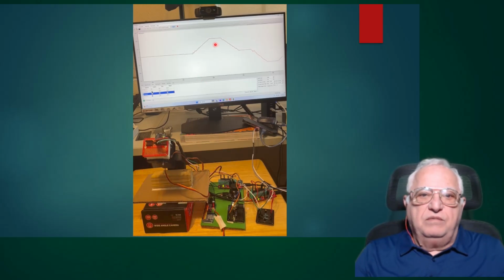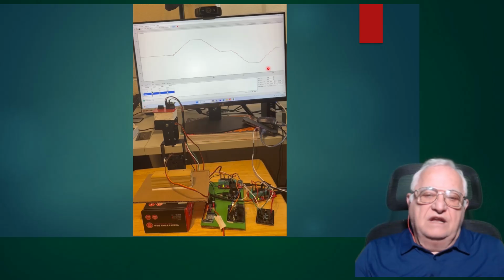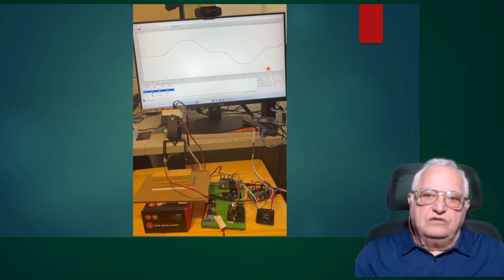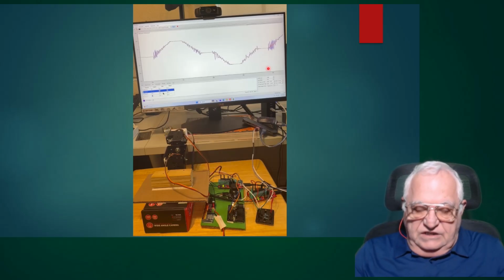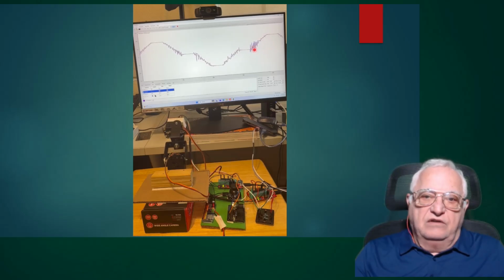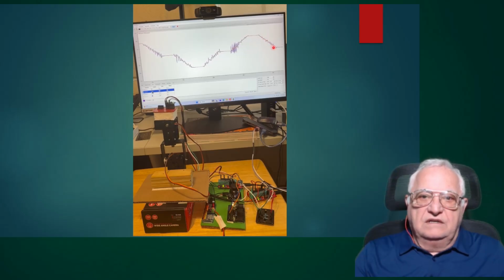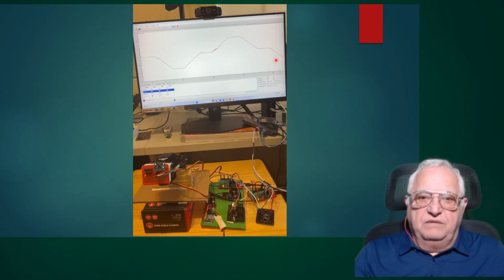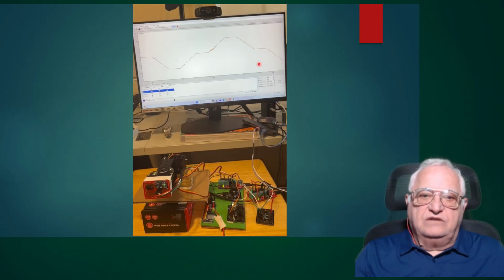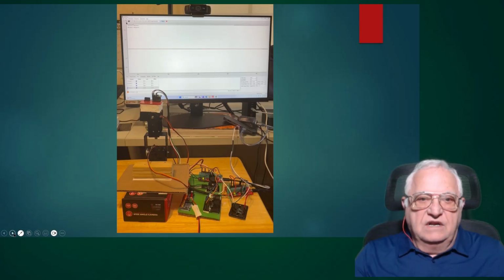So you can see how the complementary filter got rid of a lot of the issues that we had with the vibration, and also you're using mostly the gyroscope data, but we're correcting it using the accelerometer. So you can see again here the data, and how it gets rid of the vibration, and we can read the data so it's usable. What we had before, it wasn't. So now, this is simulating the pitch. Now let's do the roll.